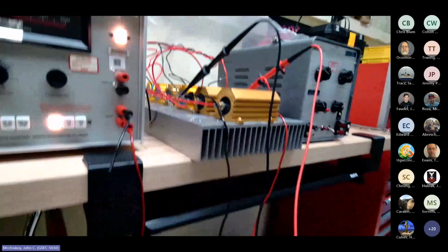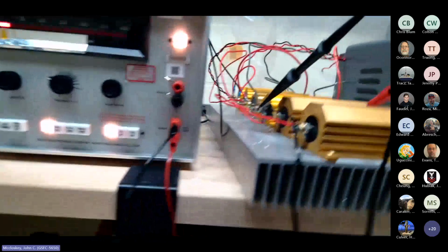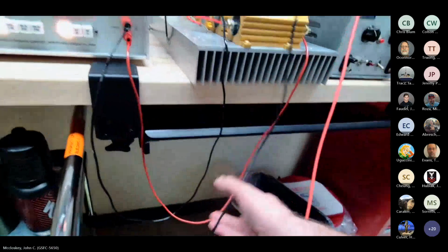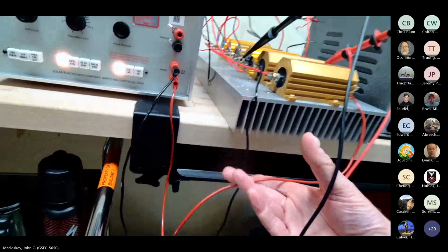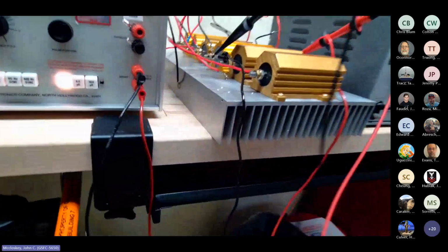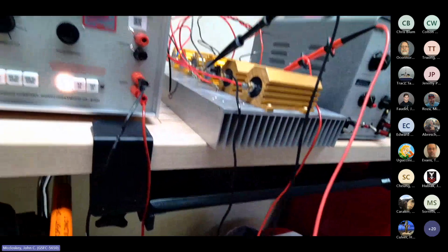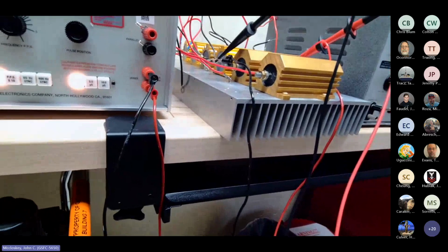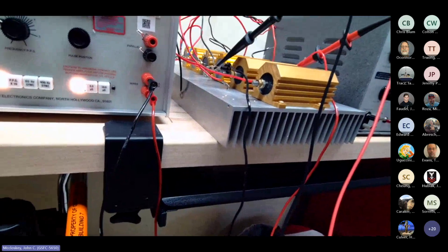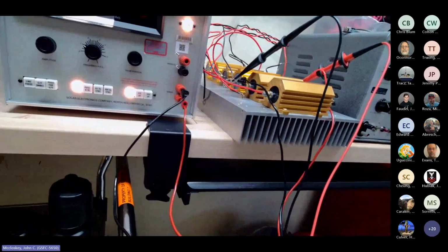Well, the source impedance of this generator is about 5 ohms. We're going into 5 ohms. Does this look like a 5 ohm transmission line? No. It's probably a couple hundred ohms, and probably not consistent from one end to the other. Now with the 10 and 5 microsecond pulses, those are slow enough that it doesn't matter. Compared to the rise time of the waveform, this connection is still electrically short.